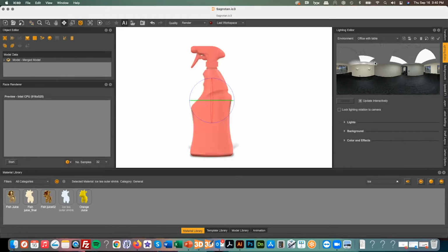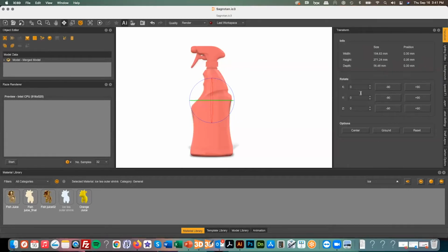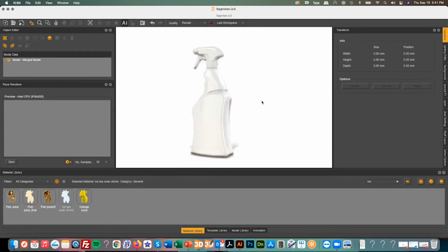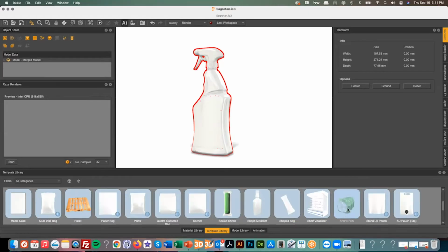So I need to actually grab this guy. I need to rotate it in the same degrees angles of what I would if I was putting it on the actual production line for shrinking. Okay, so in this case, I'm going to move this 334 in that direction. So minus 26 degrees. And then I can then select that. I can then drag out the shrink template.